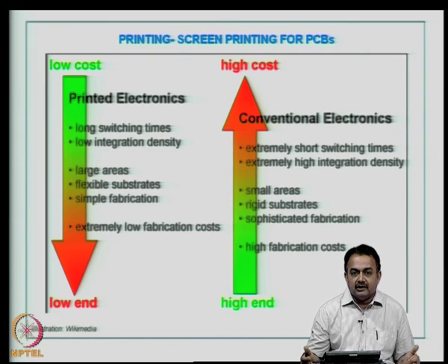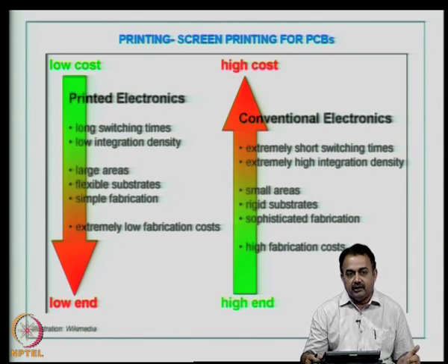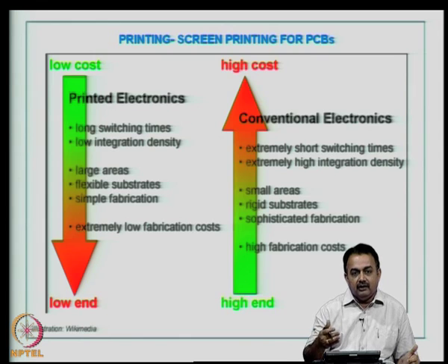Screen printing of various inks onto various surfaces like your t-shirt, or simply printing your invitation cards, or simply printing inks onto walls or any surfaces to provide a legend, right. So, the same technology can be used for printing your tracks and pads onto the surface of the laminate structure, which contains the copper and the dielectric material, and you cure the ink